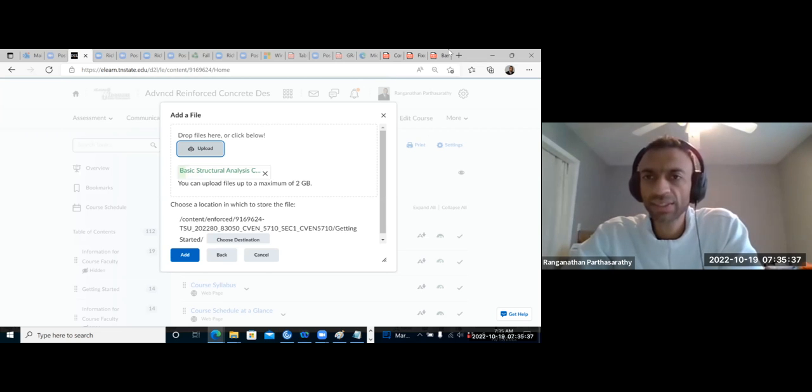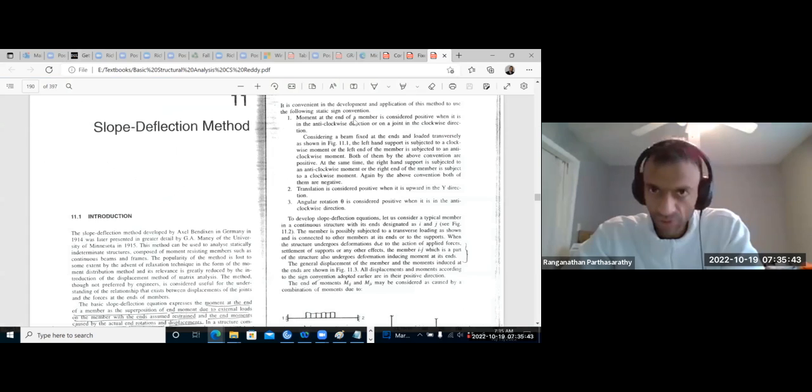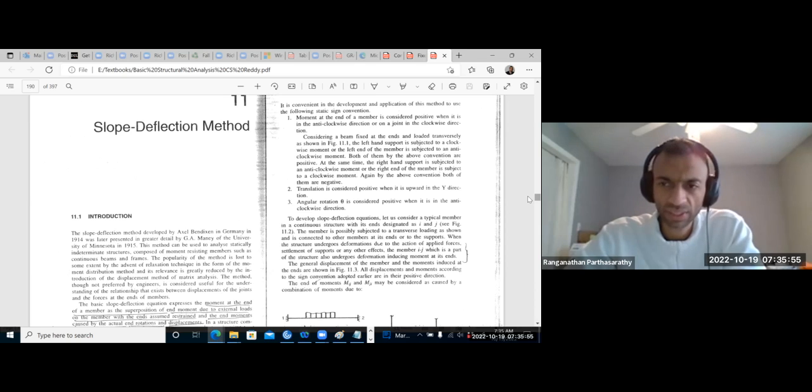Okay, it is uploading. And now you can see here, moment at the end of a member is considered positive when it is counterclockwise, anti-clockwise, and for joint clockwise. That's the same convention we are also following.